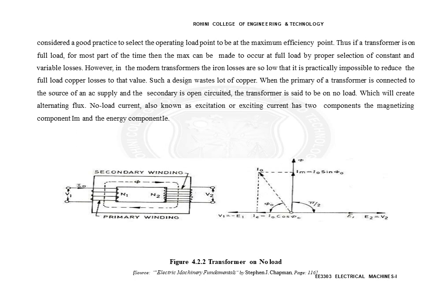The eddy current losses in the core arise because of the induced EMF in the steel lamination sheet and the eddy current formed due to it, where t is the thickness of the steel lamination used. The dielectric losses take place in the insulation of the transformer due to the large electric stresses. In case of low voltage transformers, this can be neglected. For constant voltage operation, this can be assumed to be constant.